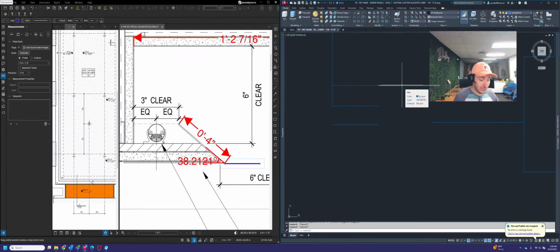So let's do that. We'll use the rotate command, highlight that line, click the endpoint here, and then we're going to tell it what that angle is going to be, which was our 141. All right, and you can see that there's something goofy going on, and that's okay. That's because I need to move this down to here, for one. And two, I need to play a game of connect the dots here. So this goes away. We're going to fillet these lines together just like this to make that angled piece like this.